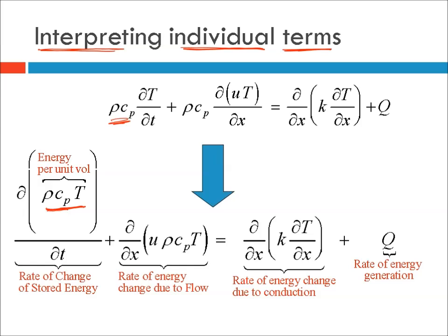And so what is the unit of rho Cp? You notice that rho Cp T is m Cp T over V, because m over V is rho. So which means what? Rho Cp T is just energy. We know this energy content is joules. So then rho Cp, the unit of that is joules per meter cube, right?